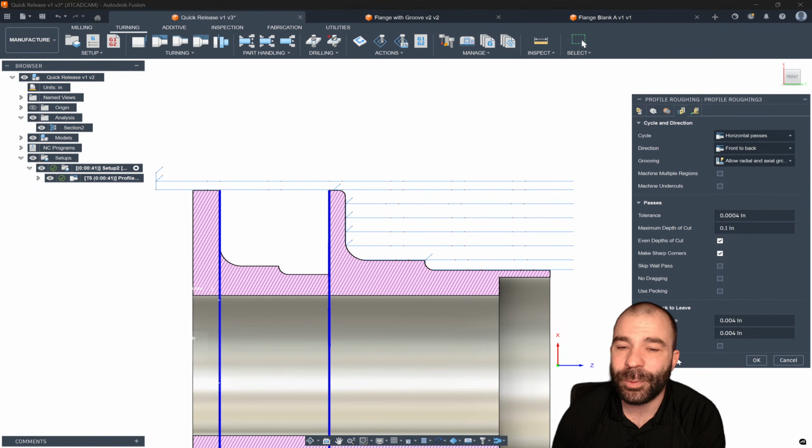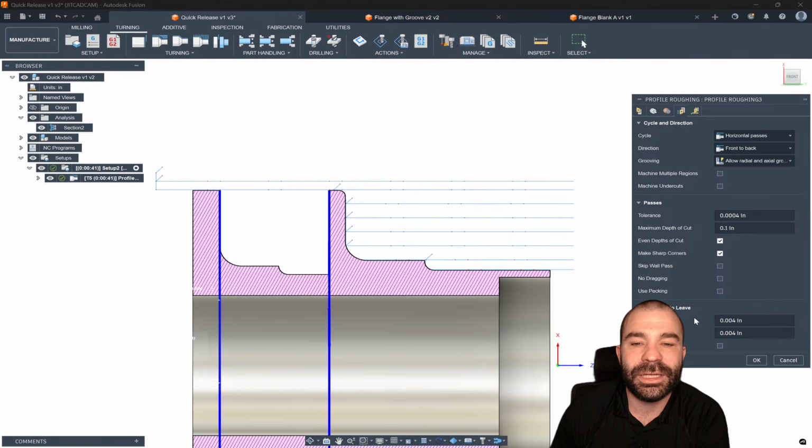It is a milling thing as well, but in some cases, your next finishing tool requires more material to get a bite. What I'm saying is, if you've ever turned a part and it seems like you cannot get a consistent finish pass, in some cases you are no longer cutting, you're rubbing the part, right? Or you start your cut and it makes a little bit of a cut and then it kind of stops and falls off. This is all the ability to adjust the amount of stock that we're going to leave on that part.